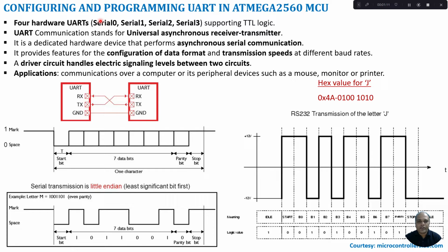In this tutorial, I will be using serial 2 communication for transferring the data from your microcontroller to PC and from PC to microcontroller. And this UART supports TTL logic. As I said, UART stands for Universal Asynchronous Receiver Transmitter, which means the data transmission happens asynchronously, without the help of a clock signal.